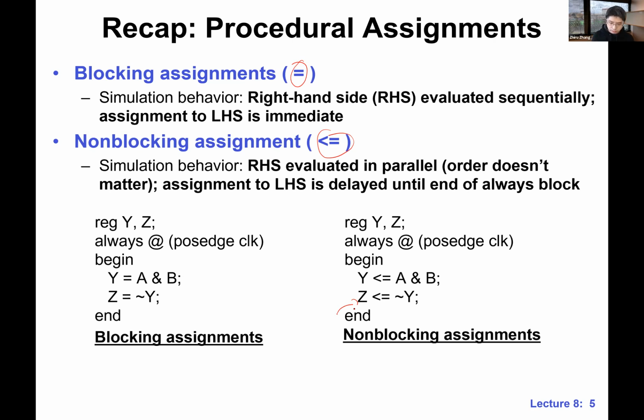So I told you one trick to read these things. For blocking assignment, you can just follow the order, from top to down. And for non-blocking assignment, you read it this way, you reverse the order. This way, you will get the simulation behavior right. Again, this is just simulation behavior.